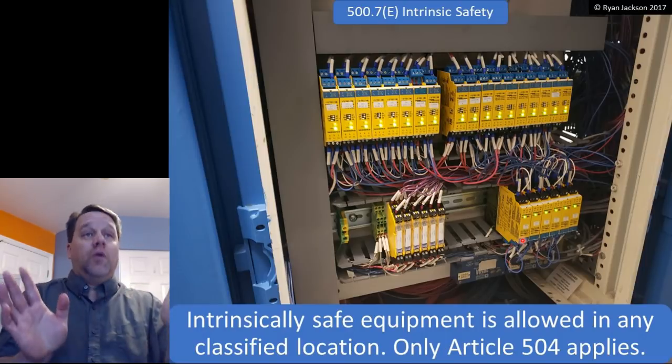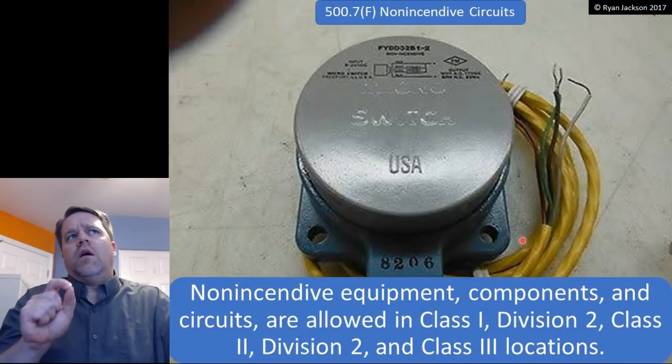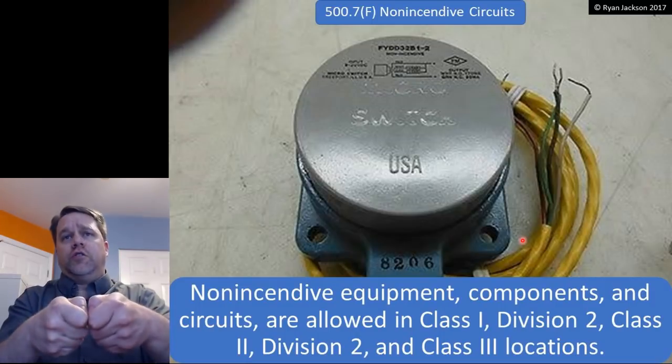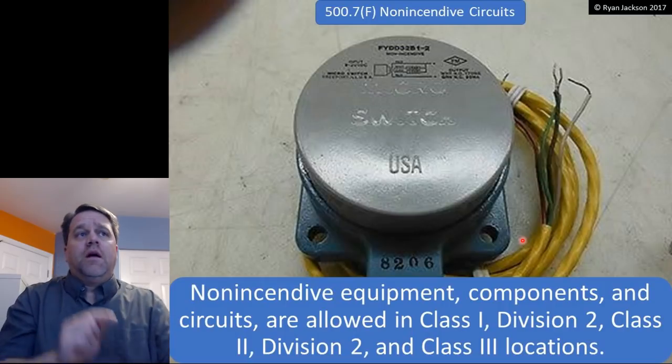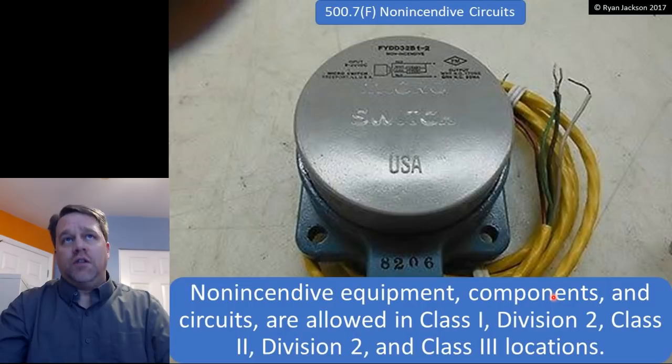No matter what you do with it, you can't create an ignition. With a non-incendive circuit, you can't create ignition under normal conditions, but you can create ignition under short circuit conditions. And because of that, it's only allowed in Class 1 Division 2 locations, right? Not Class 2 Division 1.